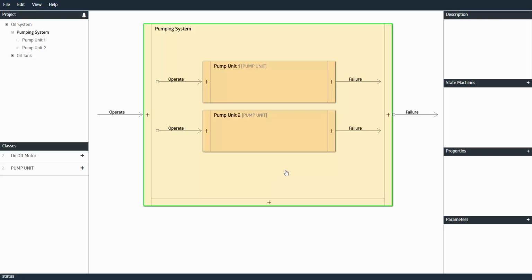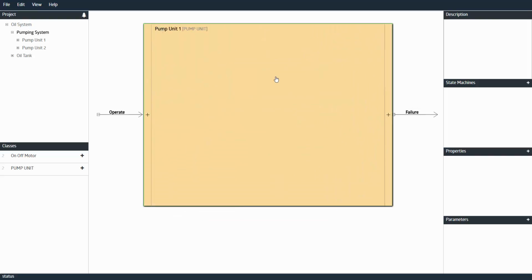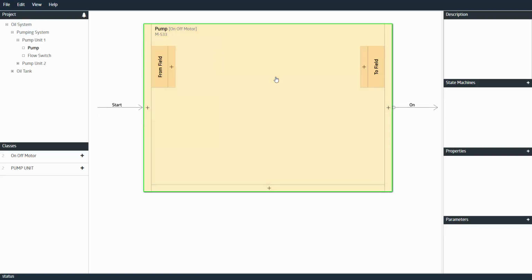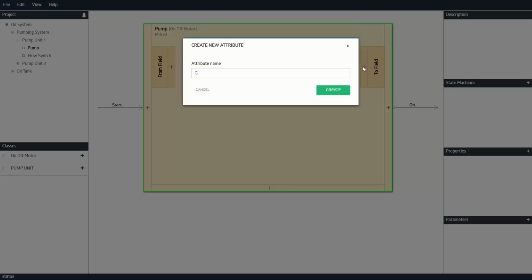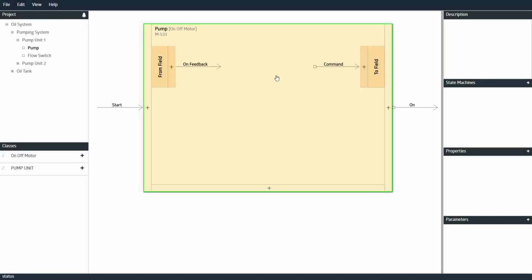Each component may have one special subcomponent called field. It is important to remember that we are designing the control system of a facility. Eventually, this control system has to send and receive signals from the actual physical equipment, or the field. By sending a signal into the field, you define a physical output of the control system. Similarly, by receiving a signal from the field, you define a physical input of the control system. These physical I/O will later be associated to addresses in the PLC.